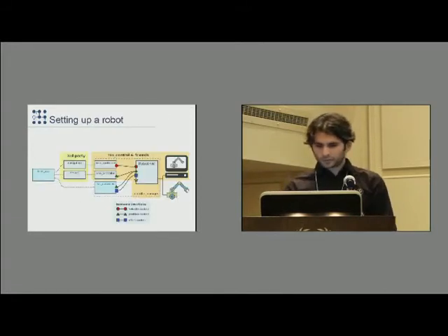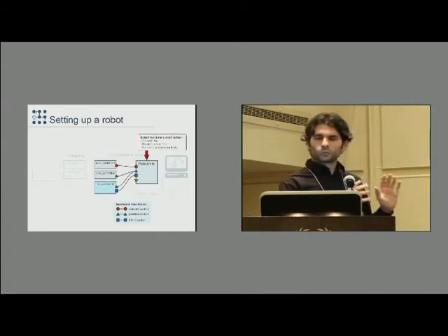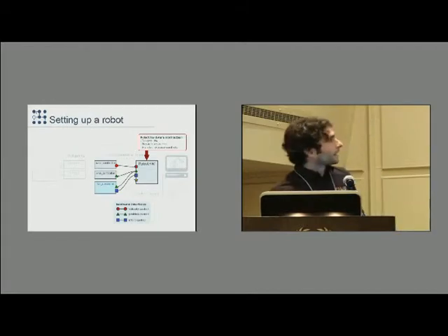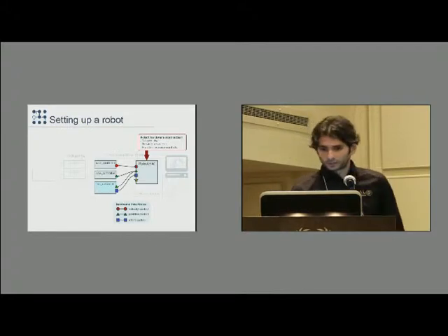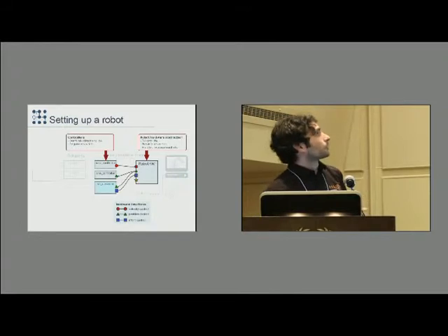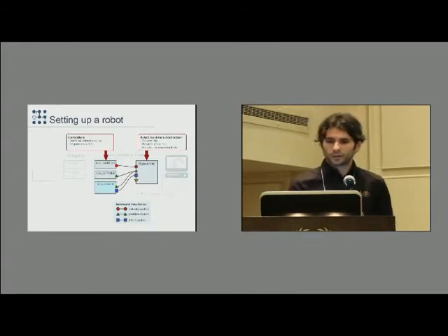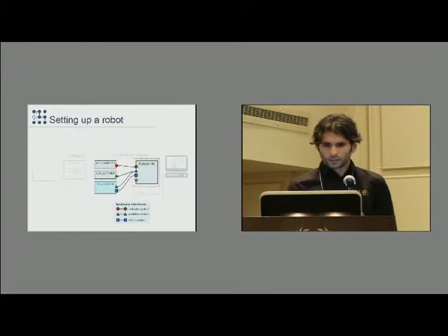So, familiar image, we're going to concentrate right now on the part that pertains to ROS Control. So we have that the robot hardware abstraction is the guy that talks to hardware. This is the one that provides resources, like joints, and it also handles resource conflicts. On the other hand, we have controllers. These guys don't talk directly to hardware, and they require resources that are provided by the hardware abstraction. So let's focus first on the hardware abstraction.